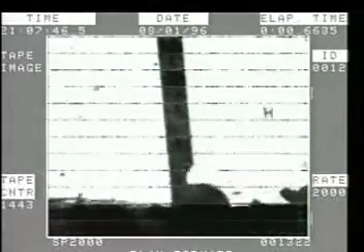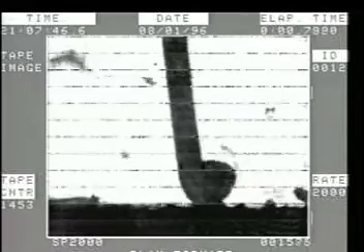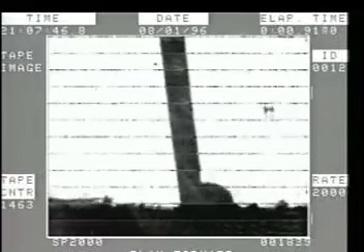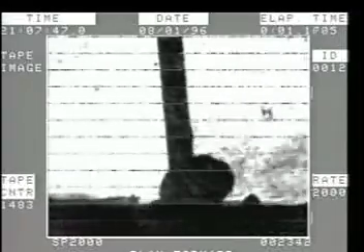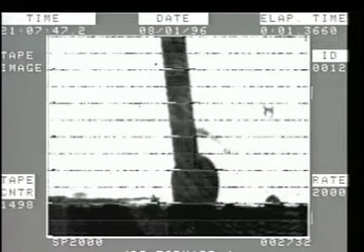The violence of the process is shown by the large droplet size. The arc is not forming anywhere on the droplet. A current density high enough to pinch off the droplet cannot be reached. Gravity and uncontrolled electrical magnetic fields dominate this transfer method. A droplet often whirls around in space as it is pushed by the arc from one point to another.